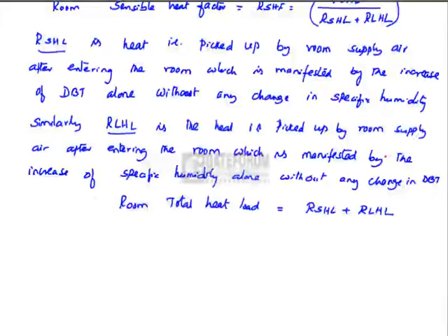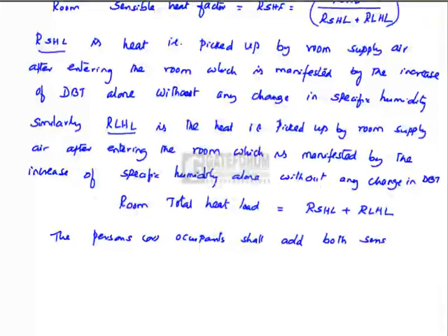If we take the persons sitting inside the room, the occupants shall add both sensible and latent heat loads, because the persons will have sweating or perspiration.